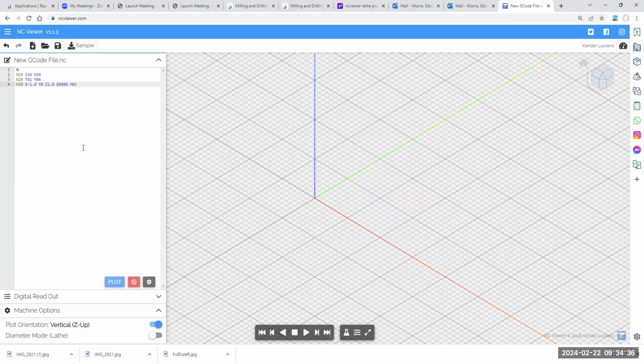Now the next line, you don't do anything with this until you do the tool setup. Excuse me, not G40, G43 H1 Z.100. In your computer when you do your setup, H1 is the tool length offset for tool number 1.